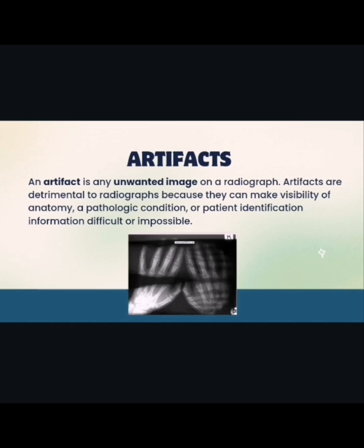Artifacts are marks that sometimes appear on the processed radiograph. Radiographic film is pressure sensitive, so rough handling or the imprint of any sharp object is reproduced on the processed radiograph. Creasing the film before processing produces a fingernail-appearing artifact. Dirt on the film or on the intensifying screen results in spot artifacts.